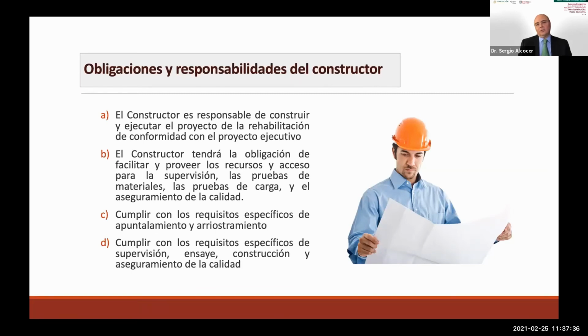As we all know, a project is a chain of different steps that need to be taken as stated in the project, and construction is no exception. In the case of structures that are going to be refitted, the role of quality assurance and material quality is paramount. If we're talking about the joints of new concrete and anchors, we need to put epoxy, but we need to use normalized epoxy or standardized epoxy.